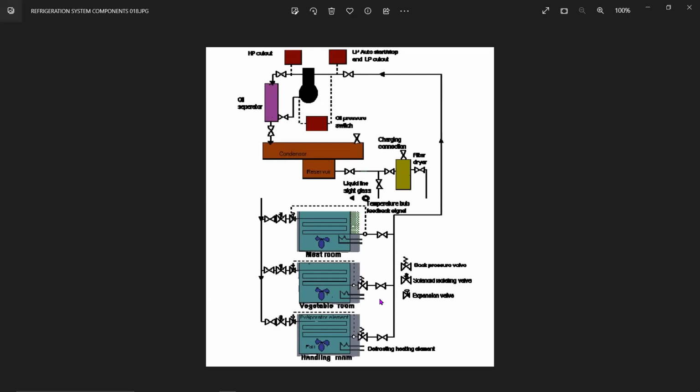But one more thing is there कि what I was seeing is I have seen systems where they have given a capillary design. Okay, instead of a back pressure valve, they have given a capillary tube, very thin tube. And the idea is that the systems are not too large in that case. That means veg room, meat room are small rooms, not like for a normal ship, you have not that larger rooms. ठीक है, छोटे छोटे रूम्स ही होते हैं, ठीक है, 20-22 लोग जहाँ पे, ठीक है.